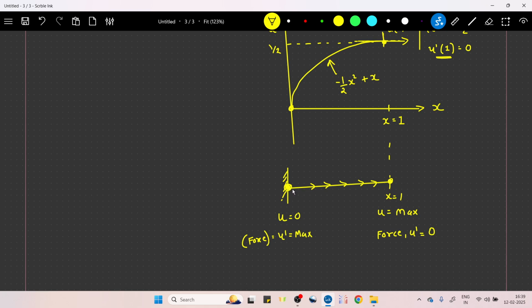You can also understand the physical significance when we are pulling this rod from this end. We can imagine that this particular section is going to experience maximum internal force, because it is impacted by this complete rod length. If I take this section as I explained earlier, let's say if this is half, this is going to experience only half of the rod force. And similarly here it is going to be zero because it is not going to experience any force. So internal force at this location is zero.